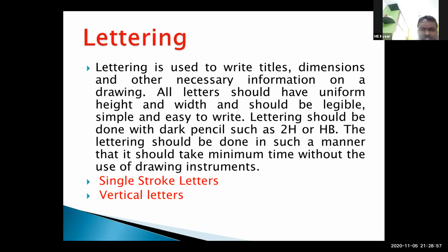A 2H pencil or an HB pencil is preferred for lettering. The lettering should be done in such a manner that it takes minimum time, without the use of drawing instruments, freehand only. Here, single stroke letters will be used, and vertical letters.